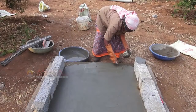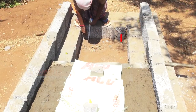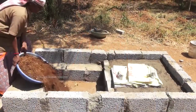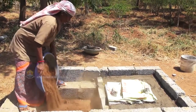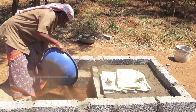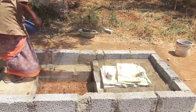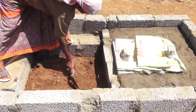We will now see the steps involved in flooring the bathing area. Measure and mark 10 centimeters on the foundation from the ground level. Fill the area with mud till the 10 centimeter mark.